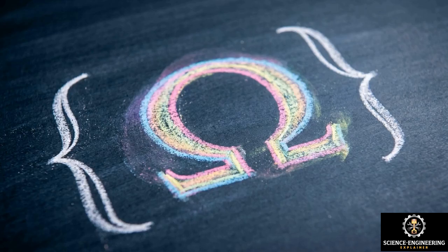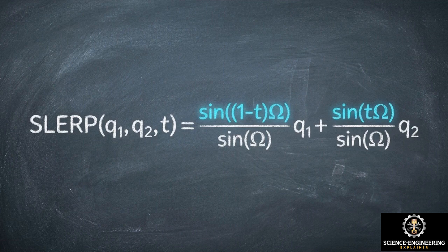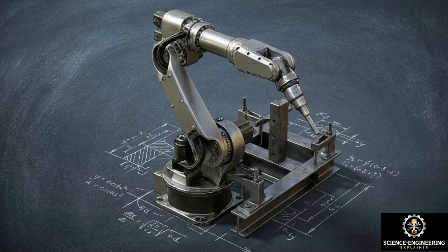The algorithm extracts the half angle between the orientations, represented by omega, using an arc cosine function. That angle is fed into the final SLERP formula, which applies a sine-based weighting to smoothly blend the start and end values. SLERP successfully executes two-pose interpolation. It guarantees the absolute shortest rotational distance while maintaining a constant velocity in the physical hardware.